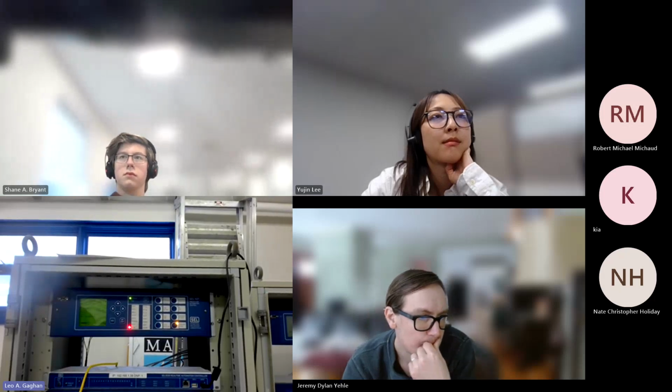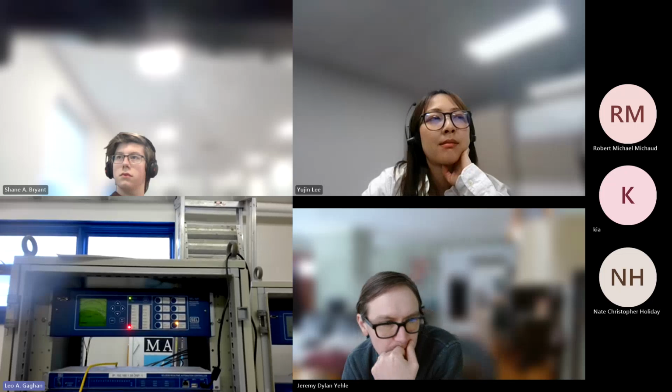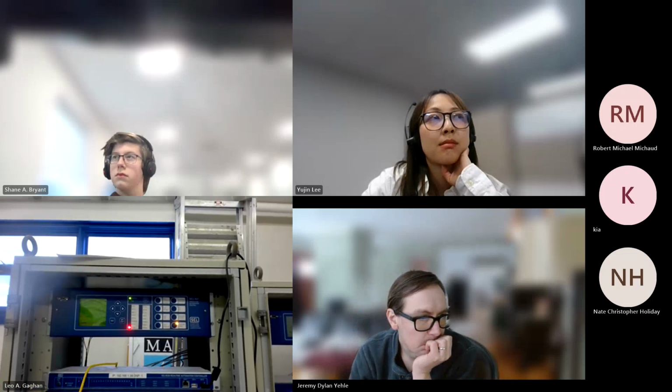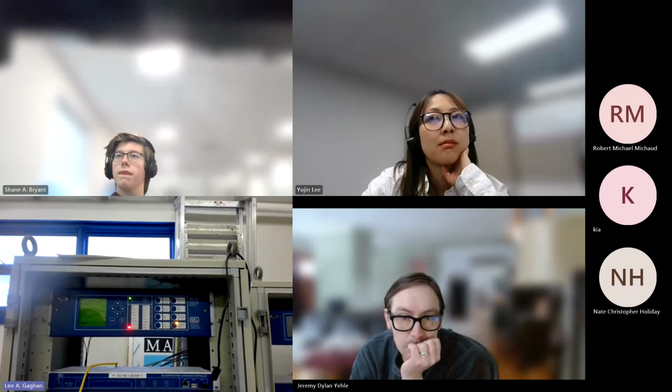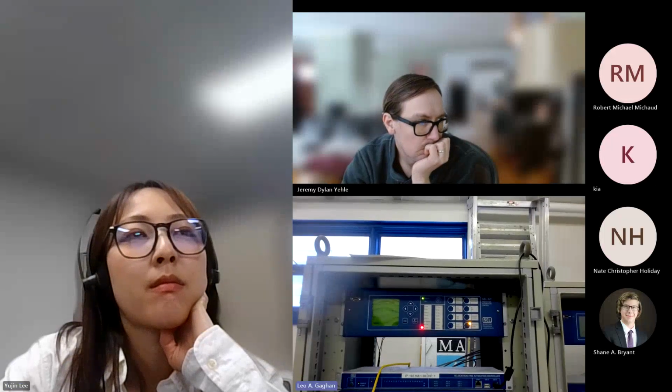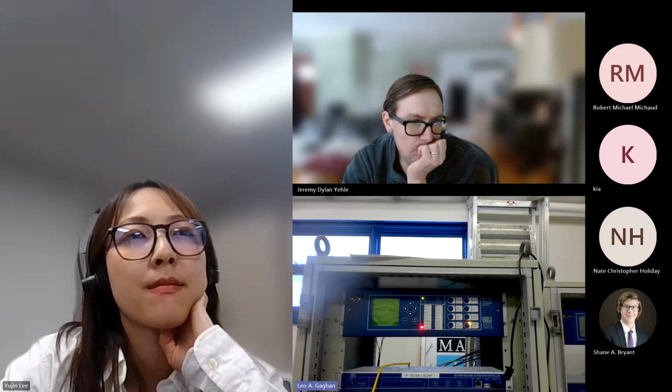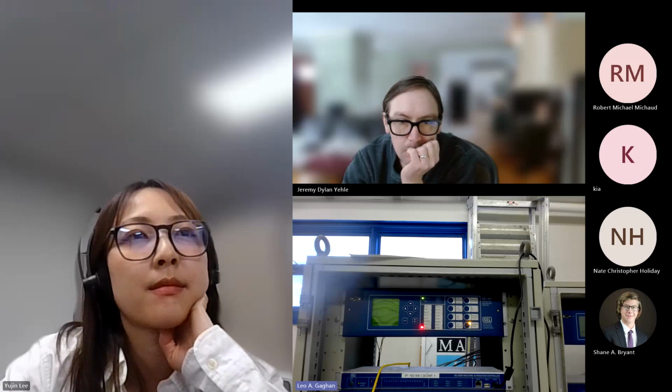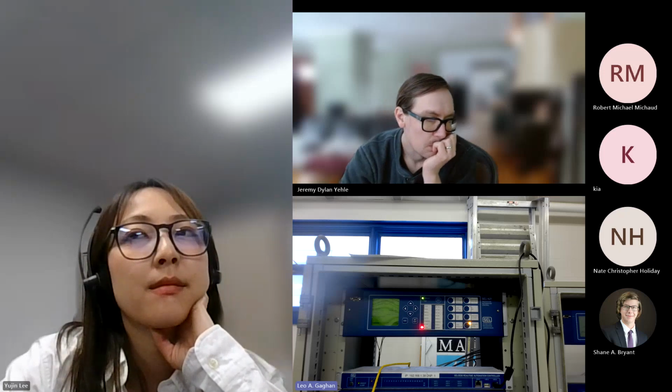So, the next one that we have here is a test mode. It's a very similar toggle. What happens here is, again, you push the push button. The only difference of this one is when you're in test mode, that LED is going to flash because it's got this flasher right here. That's just logic that feeds into itself, and it turns itself on and then it turns itself off automatically. The relay's got a test function. If you want to do any test trips, everything that we're really doing is testing, right? This isn't in a real life scenario. There's no voltages occurring, so we're testing.